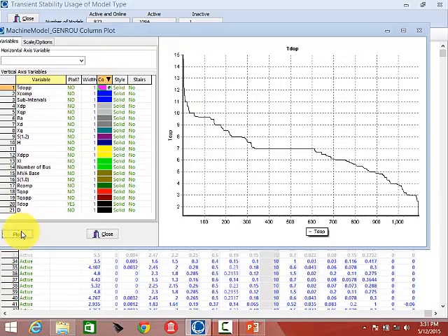Some of them go to 0 because that's a condition for a salient pole generator. But do I say this is a valid range? If somebody puts in 80 for that, is that right or wrong? Probably wrong, but maybe it's right. But you can get access for that. So if you're seeing something that's behaving strangely, you can look at all the models of that type and say, is this an outlier? I do that a lot. When we see strange behavior, I'll look and say, is this an outlier compared to what the rest of them are doing? And we let you see all the model parameters in the case real quickly.